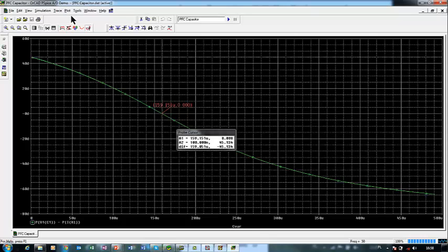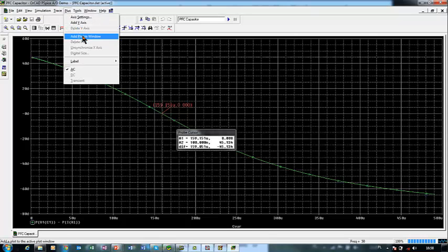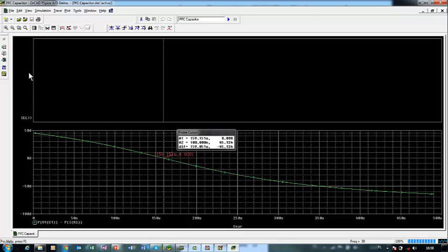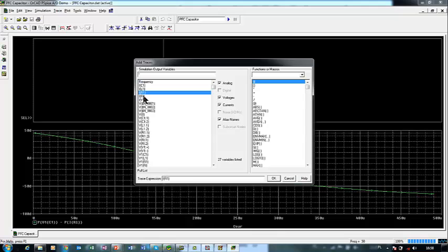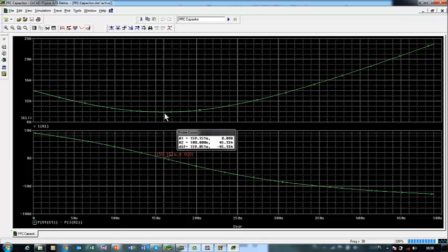We may add another plot to this window, add plot, and now add trace, which is the current that flows through our load, sorry. Okay, and our minimum designates this capacitance, which is obviously the same, 159. Using toggle cursor and find minimum, we may find this value, exactly the same value as before. Okay, that way we have completed calculations for this exemplary circuit.